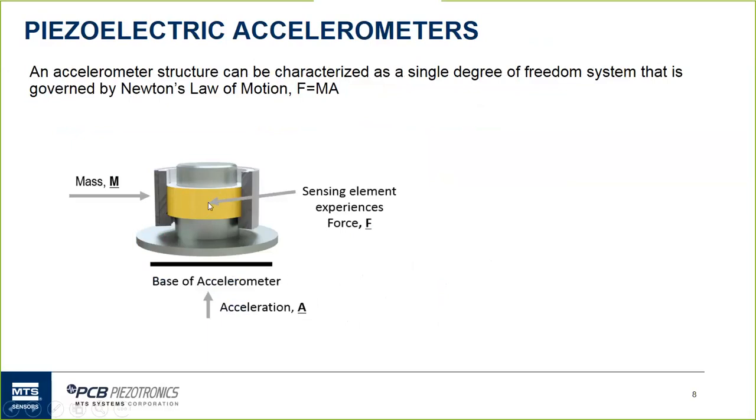That sensing element is, in this case, an annular shear design. And that sensing element can be naturally occurring piezoelectric material like quartz, or could be using man-made materials like ceramic elements.